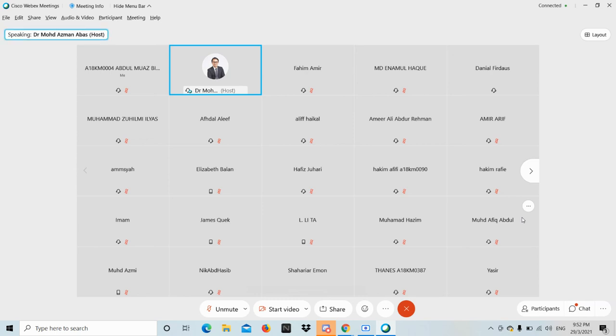They purposely have that because they wanted a higher RPM, but they compensated for the disadvantages of the shorter stroke, because a shorter stroke definitely has poorer combustion, but they compensated that with better air delivery through the VTEC system.